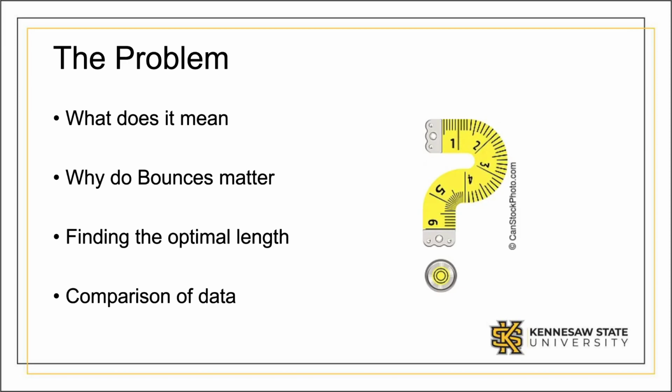Why do bounces matter? Because if the bounce is going away from the engine when the valve is open, or when the air is flowing away from the engine when the valves open for the air to come into the cylinder, then it will be resisting airflow, and that's no good. We want the bounce going towards the engine whilst the valves are open, to have more air into the engine.